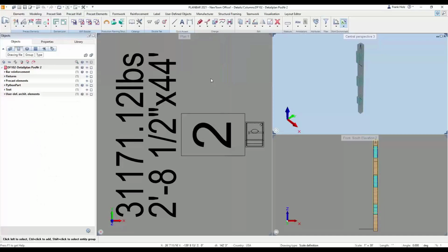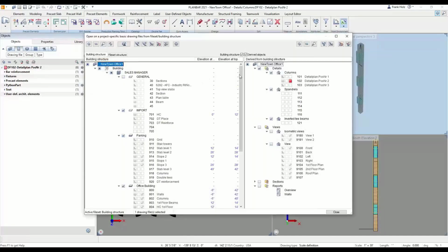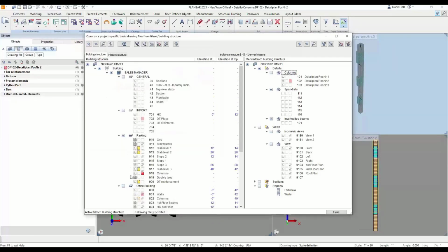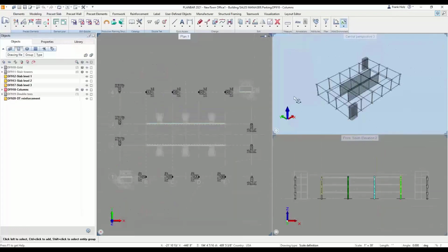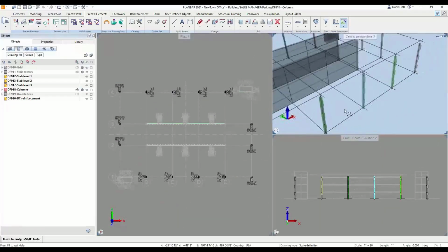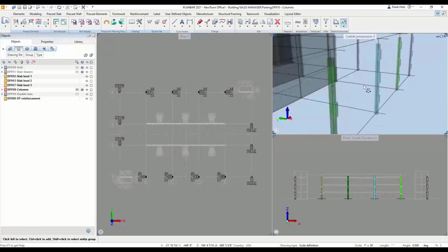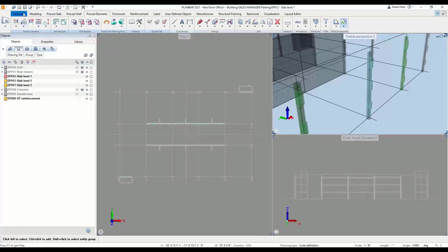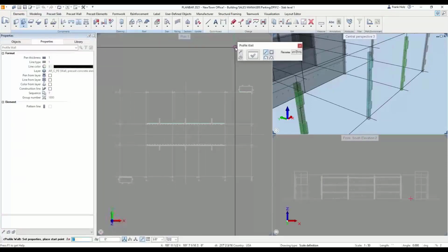ALLPLAN plan bar is very quick with even a lot of details in your model. But if you have somebody working on a slower, older computer, this is nice just to keep everything separated so it doesn't slow down maybe some of those older machines. But like I said, it's very quick. So rendering all of these bars inside of your model is not a problem at all for us. And this synchronization function really shows off one of the ways in which this is intended to serve the precast market. I can control an entire mark number from one location.